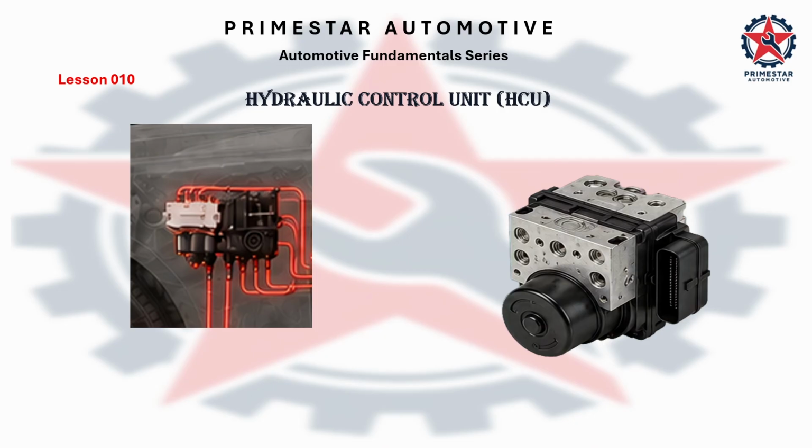The hydraulic control unit contains high-speed solenoid valves, normally open and normally closed, along with an internal pump. It cycles pressure through 3 phases up to 20 times per second.